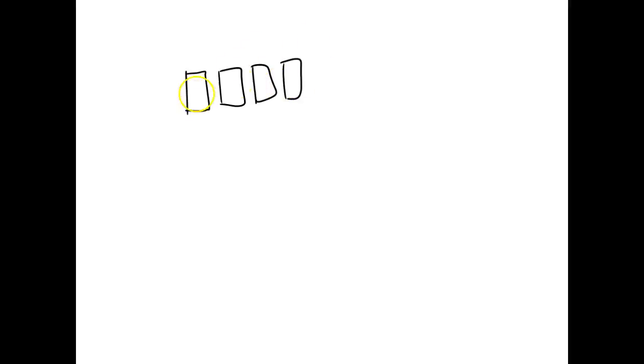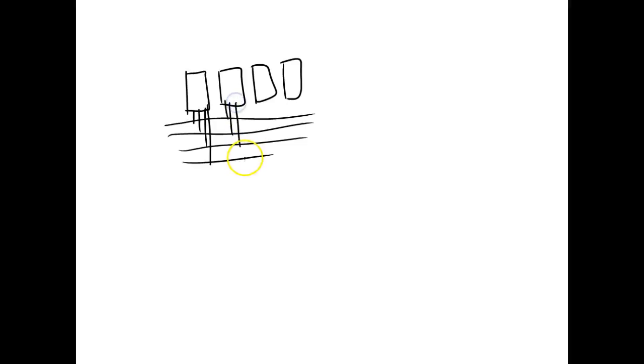They'll have 4 or 5 or 6 7447s, and they'll multiplex them. They'll share the data pins, which is going to save a lot of hardware, right? You understand that?